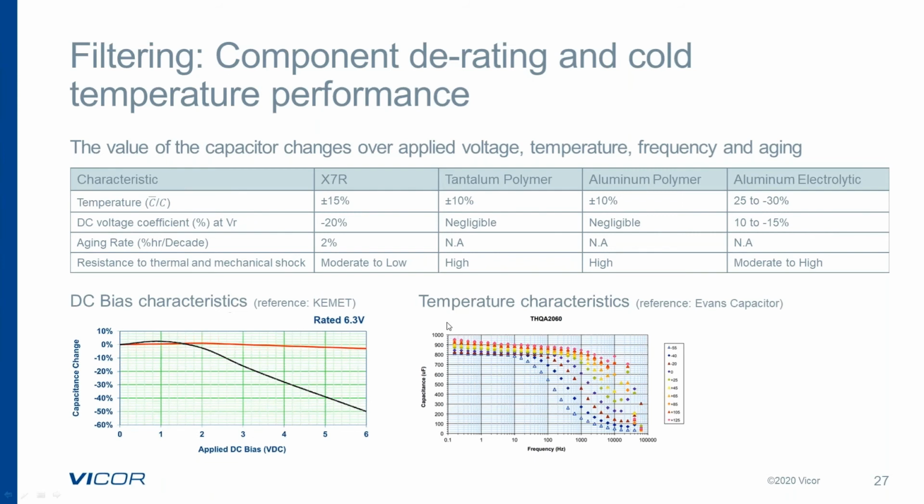Temperature is another factor we need to consider when selecting some of our components. In some cases, an electrolytic capacitor can change its characteristics quite a bit over temperature. In many cases, we need to design our DC to DC power system to meet -55 operation in the case of military applications, or -40 for industrial applications.